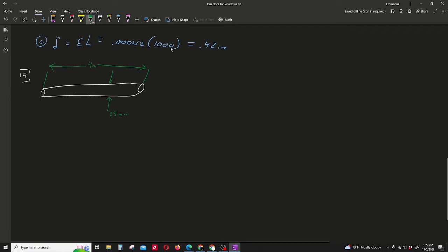And it has axial tensile load of 65 kilonewtons here. And it said it's tensile, so tension, going this direction, 65 kN. So now we can actually solve for this problem here. The first thing that they want us to solve was the stress, then we saw the strain, then we solved the total elongation. So the stress